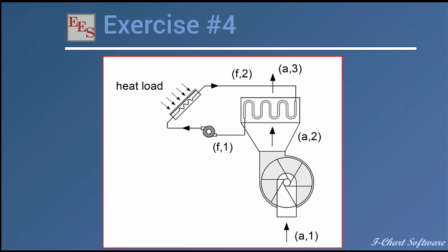And then the other thing is, I don't know the temperature of the fluid in the fluid loop. I have to make sure that if I start here with the temperature entering the heat load and it gets hotter and then it goes through the heat exchanger, the performance of the heat exchanger is such that the fluid coming out of the heat exchanger is equal to the temperature of the fluid that I assume going into the heat load. So those are two, let's call them iteration variables, that I will need to initially set, and then we'll work through the calculations, and at the end I can remove those iteration variables and start with a good set of guess values in order to close up my equation set. So that's my process for doing this.